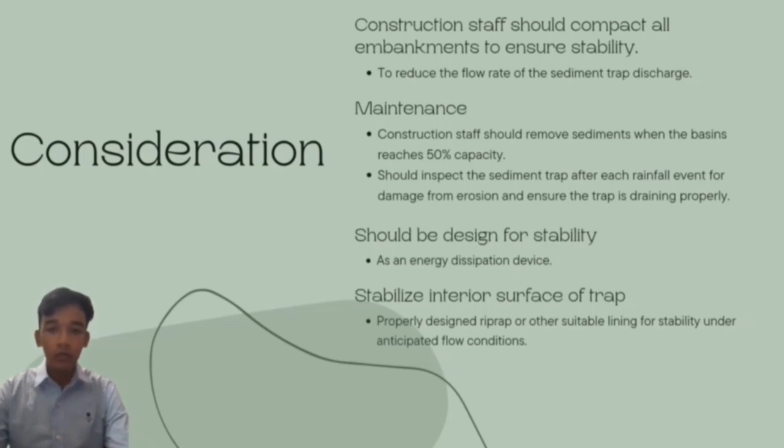Next, the outlet should be designed for stability as an energy dissipation device. And lastly, stabilize the interior surface of the trap with properly designed riprap or other suitable lining for stability under anticipated flow conditions.